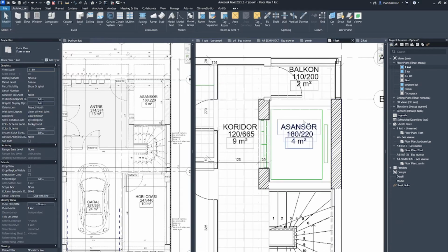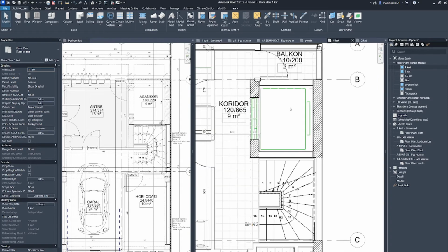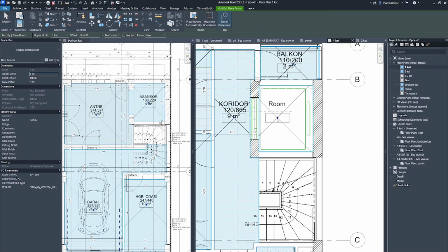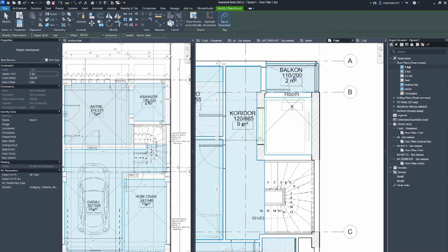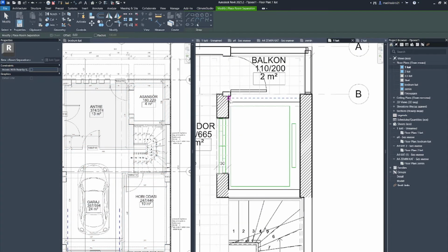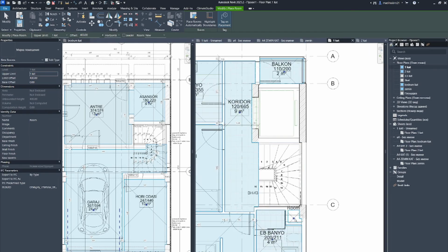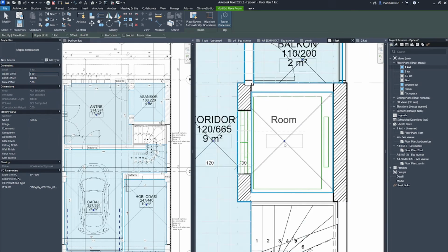But before that, I would like to show you how to make the area show up, like this one. There were some students who always have some problems with it, and I was also having some problems. So first of all, we have a room. I choose the room. If it doesn't work perfectly and smoothly for you, like it's showing different parts or something, then you have to use room separator and draw over. Like I use a square and then I draw over, and it divides automatically, so when I use it, it works again. It's like a ventilation system area, etc.